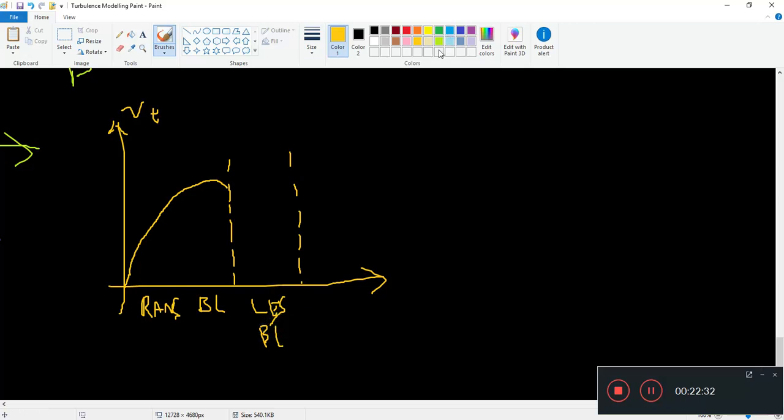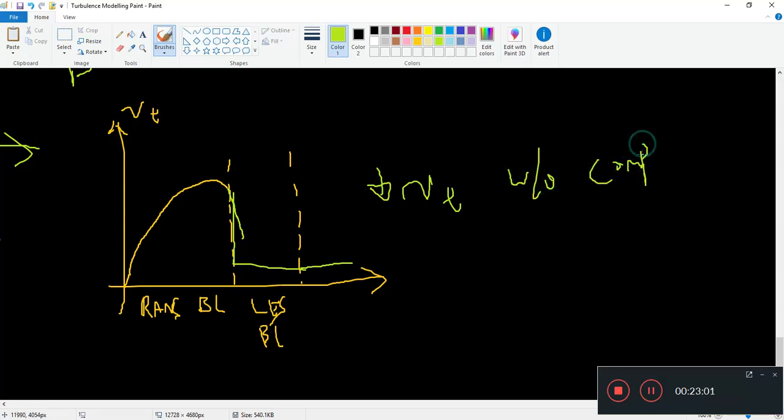Okay, suddenly there's a drop, which is kind of artificial because you switch to LES a bit early, so the makeup for turbulence isn't there. So yeah, you have a sudden steep drop here. I don't really know what this shape of the curve is, but model stress depletion means there's a sudden drop in nu t. So it drops nu t without compensating with actual flow instabilities, right?